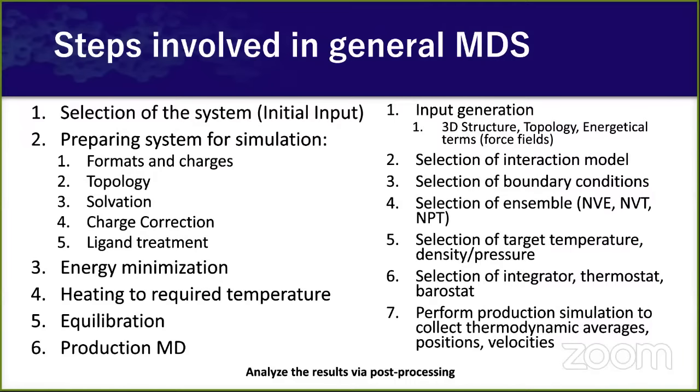Often if we don't do the equilibration and directly run the MD, there are formation of vacuum bubbles and some unwanted forces which may fail or crash the simulation because of the unrealistic forces generated. So these are the different stages through which we have to go for setting up the MD. When it comes to the actual preparation, we have to generate a lot of different files, a lot of different parameters, and consider many properties of the system before we set up the simulation.